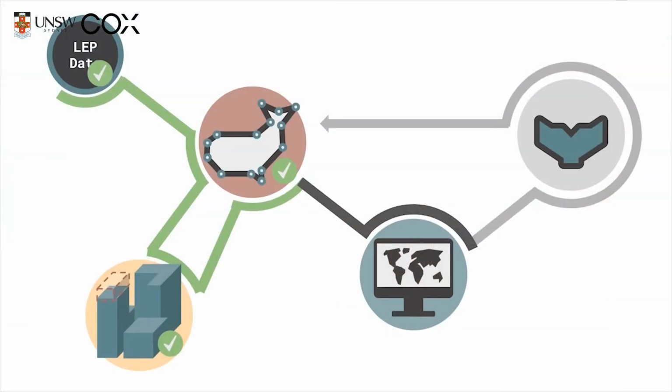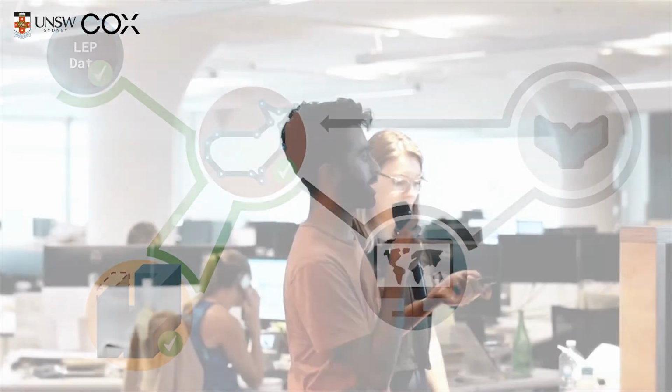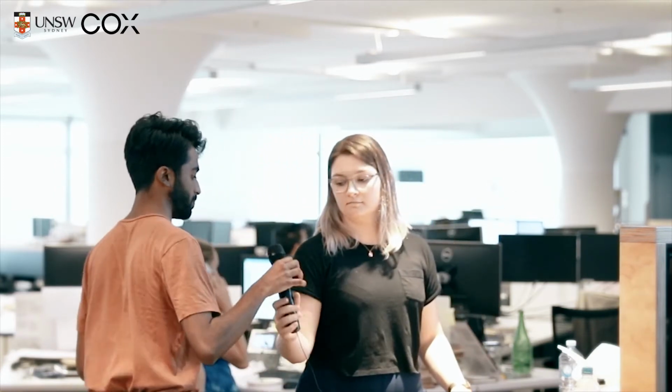Yeah. All right, so just to go back to this diagram. What we did was we got the LEP data from Oren. We used Humpback to convert it into Grasshopper geometry. And then from Grasshopper, we were able to create the building envelopes. And then from there, we can send it back into Humpback to convert it back into a WebJS format. So I'll let Mandy take over from here.